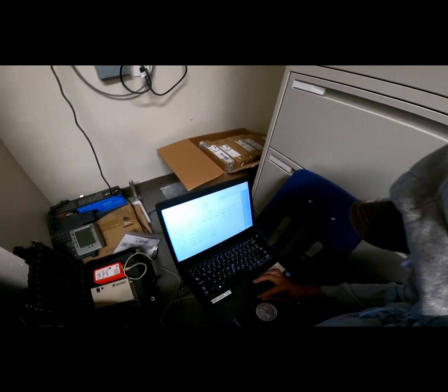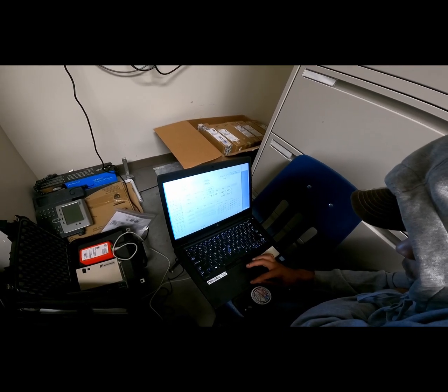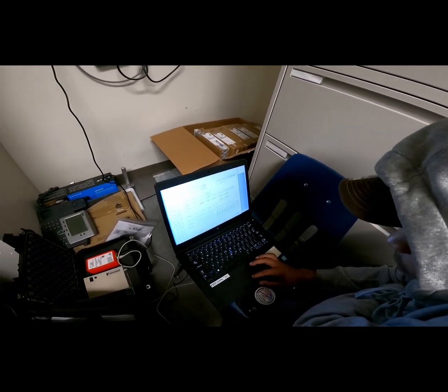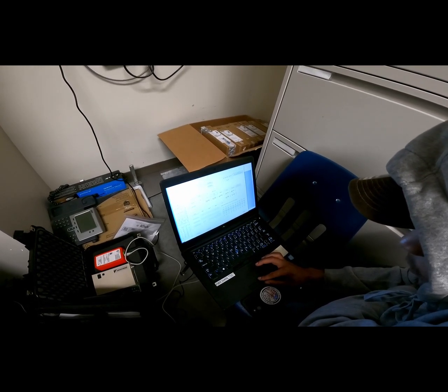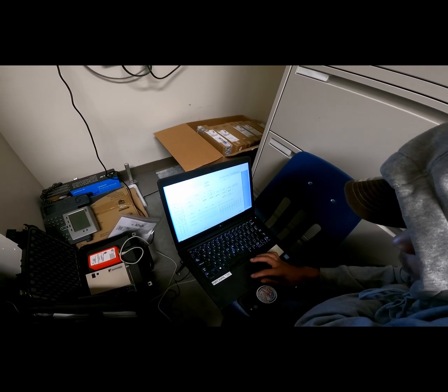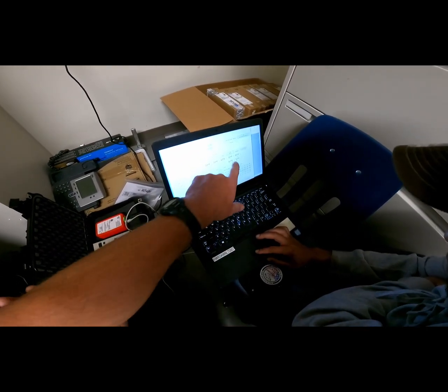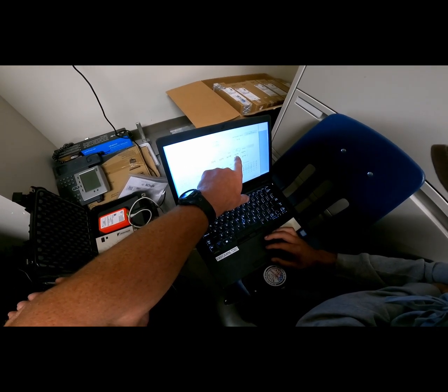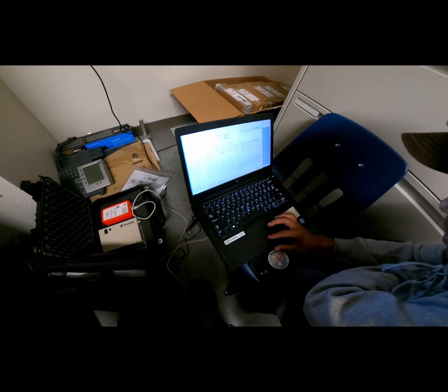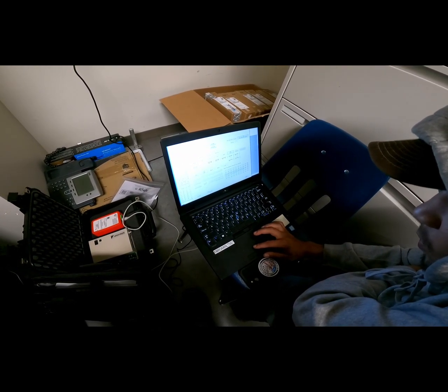Set selected addresses 21 through 28. This is probably the most important thing that you all need to be able to do: to put these things back into operation when you're done so that they don't continue to run in test mode. I would put each one in mode auto, and that means that they're going to cool above 72 degrees and heat below 67. I'd go ahead and leave it in high, and then transmit.